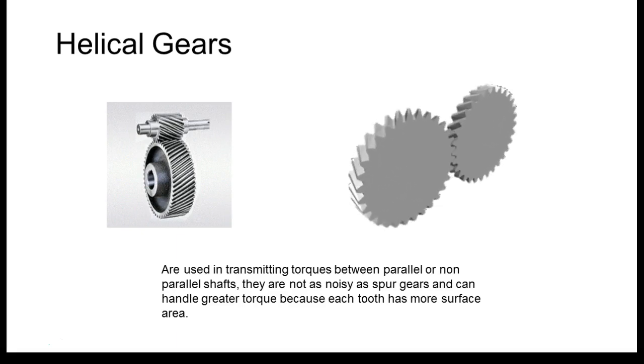Now the problem with helical gears is they generate axial thrust. The way they're slanted and pushing on one side, they're constantly trying to push each other apart, right? Or they create axial load. Are we okay?